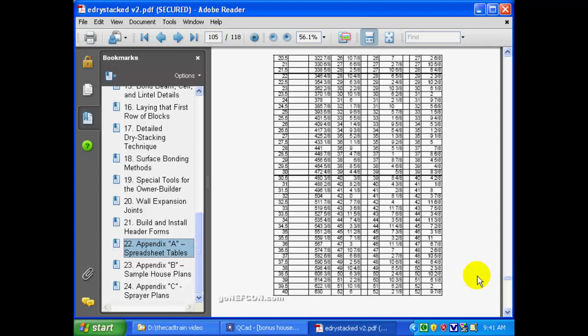And it also includes a 1/16 of an inch for wall growth, which is fully explained in the DryStacked handbook. So those 2 factors are already rolled in. The only thing we can't include in this table is the fact that a corner block is 8.0625 inches wide. And that messes up the table, so during this session we're showing you how to adjust the actual floor plan to include these corner blocks.